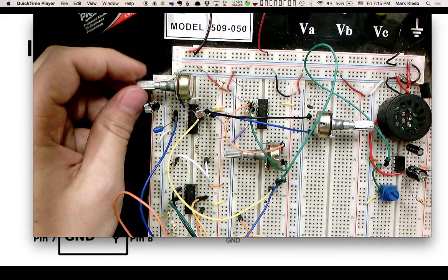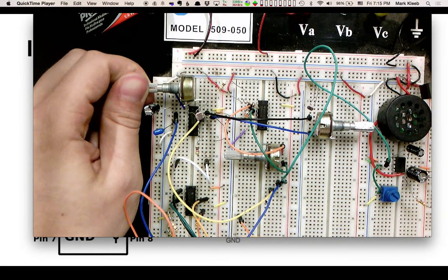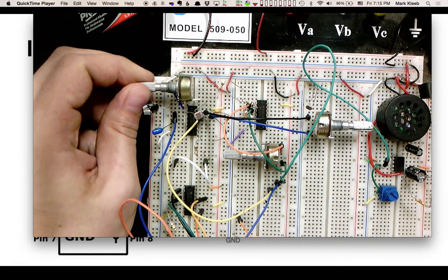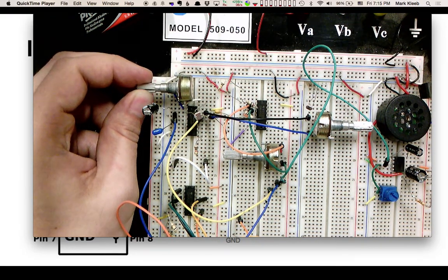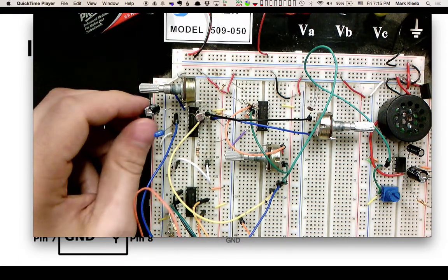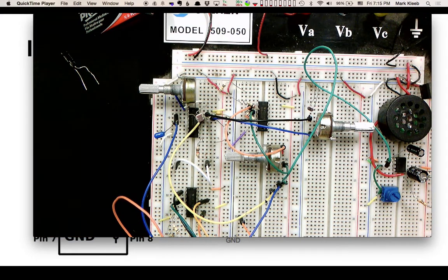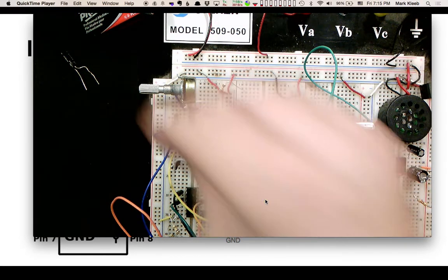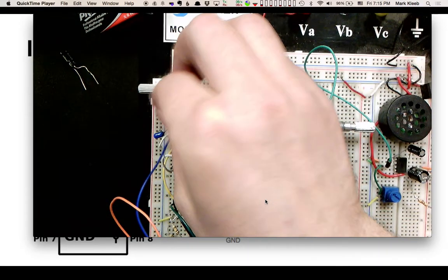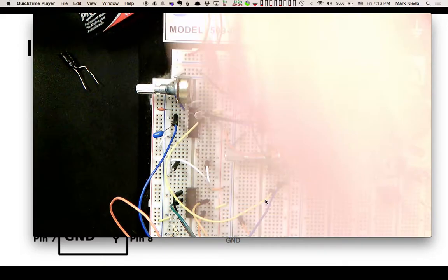That's my top end of that frequency. And of course I can change my resistor to change the cycle. But I like to play around with different capacitors and see what kinds of different sounds I can get. The general rule is smaller capacitors are for higher frequencies and larger capacitors are for lower frequencies. All right. I'm going to pop that out for right now.